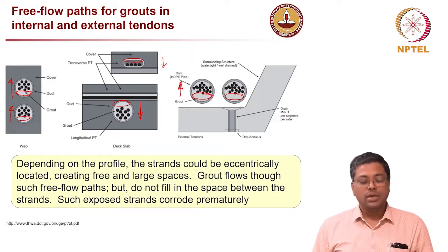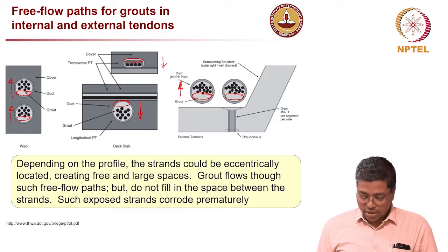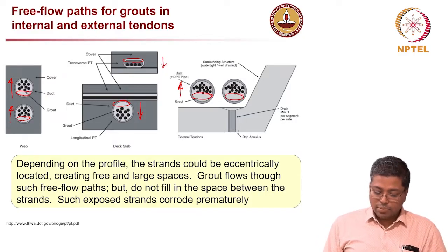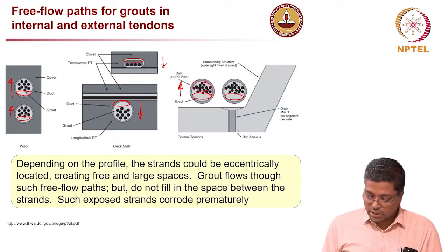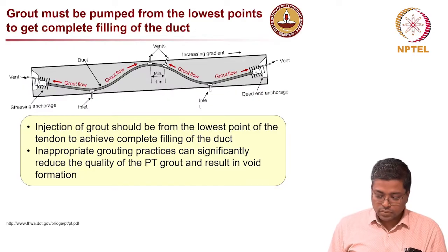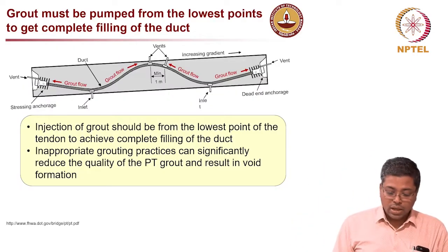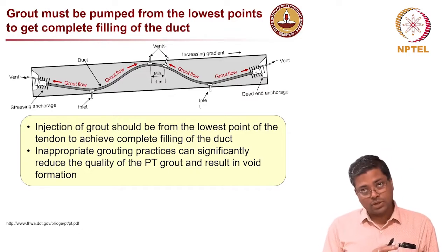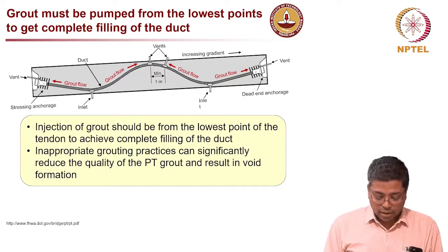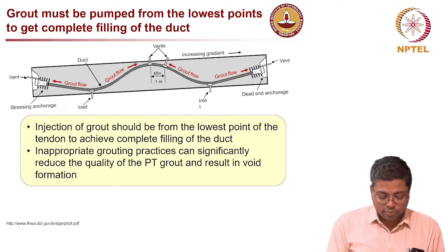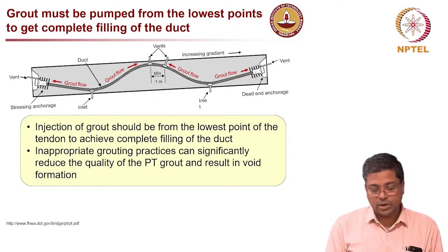But that is not the right conclusion to make, because you have to really make sure that this congested region here is actually filled up. That is very, very important. Now, for achieving that, we have to have a very good grout and also allow enough time for the grout to flow. And the best way is, instead of pumping the grout from one end of the duct to the other end,